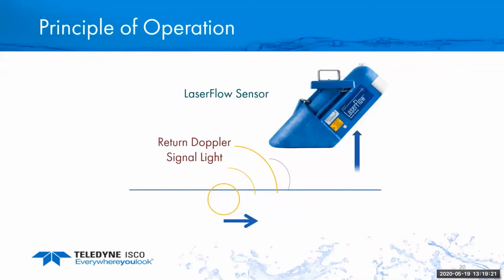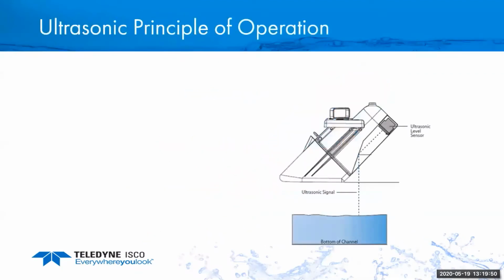Well, there's an ultrasonic sensor in the back of the laser itself that transmits, like Darrell said, the sound wave, reflects off the housing, and knows where the water is. And the key with this technology is how it reads the velocity. What it's doing is actually focusing the laser below the surface of the water. So it knows the level, knows where the water is, and knows where it needs to focus in order to get a return signal.